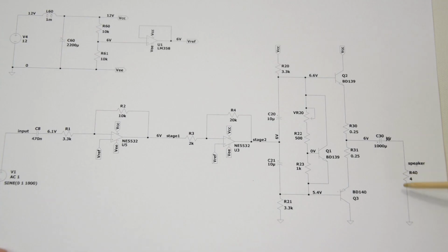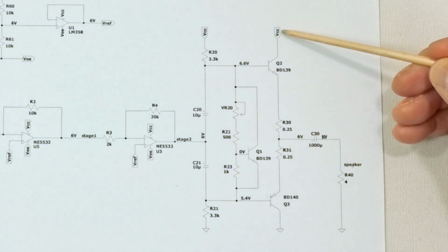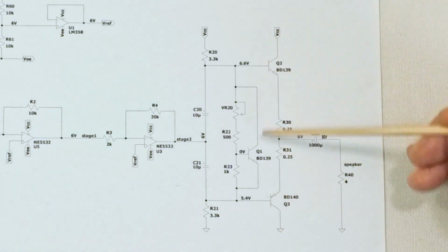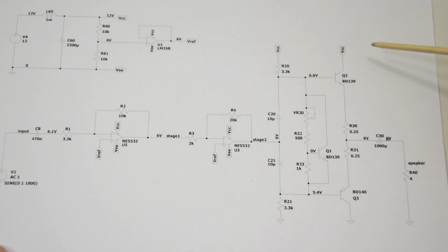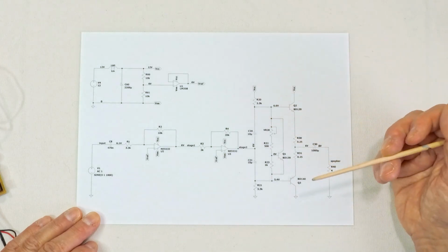The issue comes up as soon as I connect the 4 ohm speaker or the 4 ohm dummy load to the output of the amplifier. We could see on the digital multimeter that it draws a lot of current instantly. And this has to be provided by the output stage of this amplifier. But it looks like the power supply is not able to deliver this large amount of AC current to this output stage, as the signal looks like it travels back into the power rail.